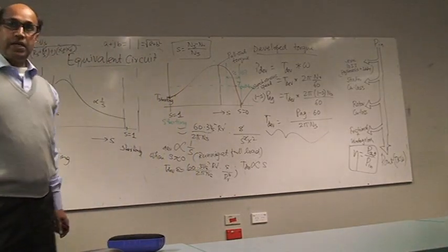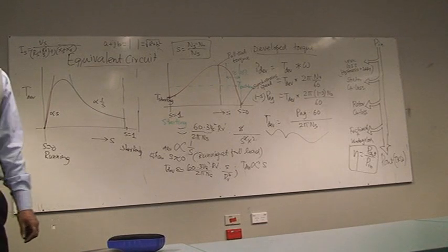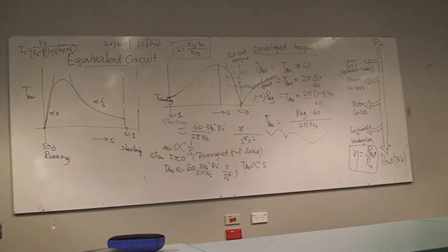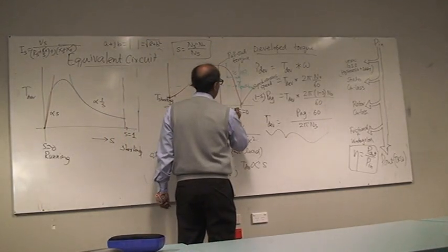So ideally, the induction motor runs very close to synchronous speed. So the slip will not be more than 10%. Full load slip will be 4% to 5%. So that's S is 0.1, maybe you can say this will be 0.1.